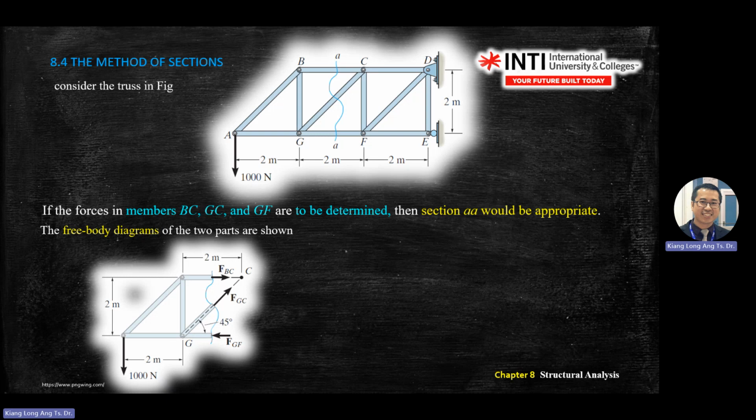and if you really don't know, you just point all the arrows out. If you really don't know, then you do analysis. All the force equals 0, x equals 0, y equals 0. You will find one of the values is negative. Then you flip the direction.